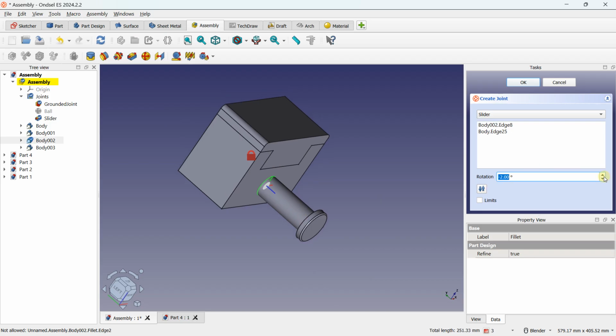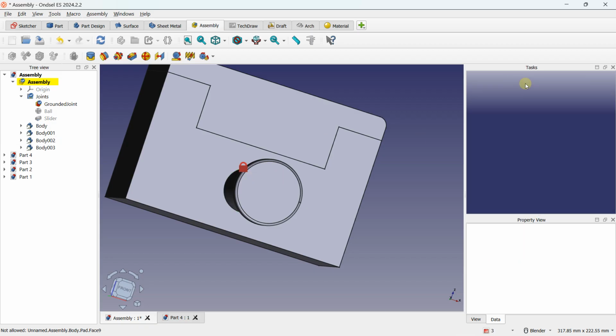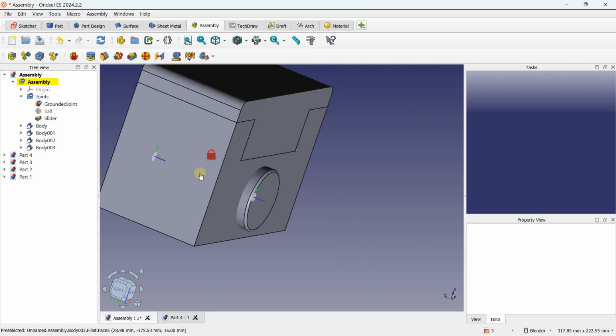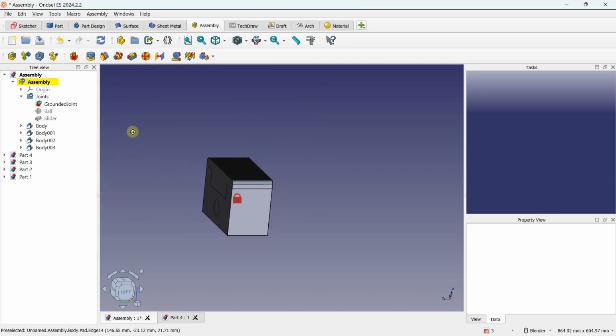And the advantage of the slider, we can create some rotation also after. So here you can turn, as you can see, the element is turning in this direction. So we can apply a value to turn. And that's it. After, if I move, I can drag and move. I have the constraint to stay on this axis, but I can drag and move, as you can see. And here it is the same.